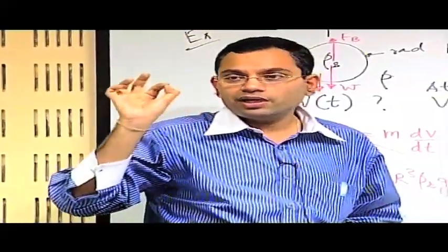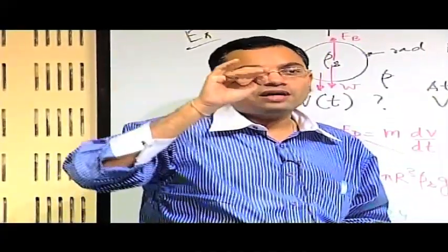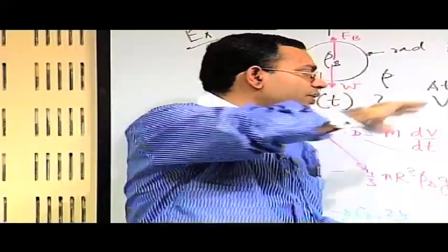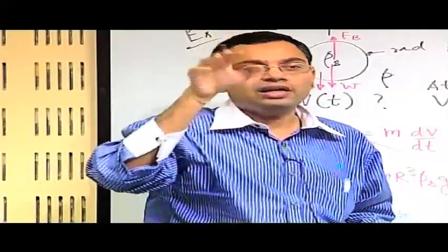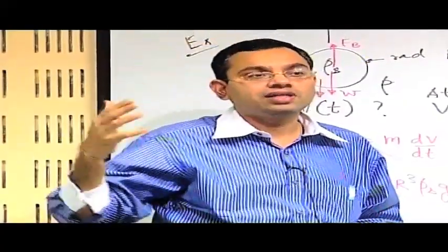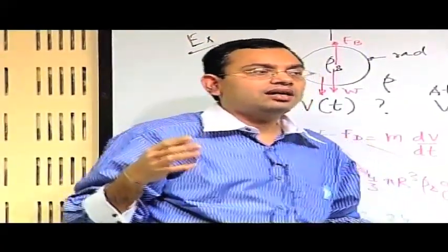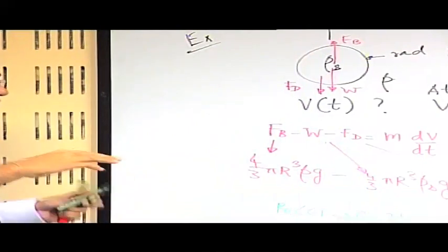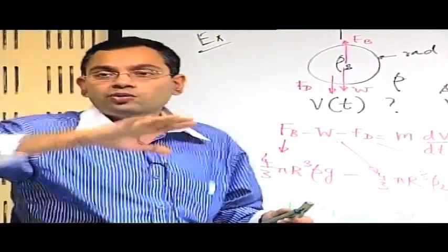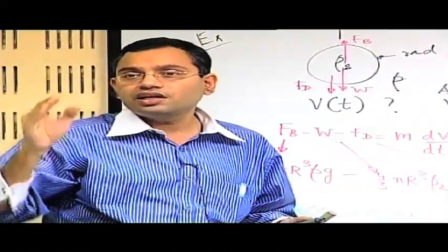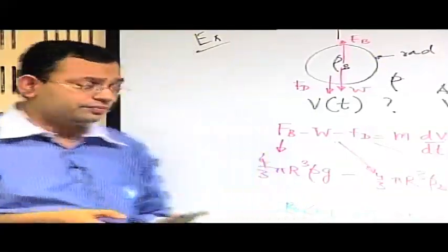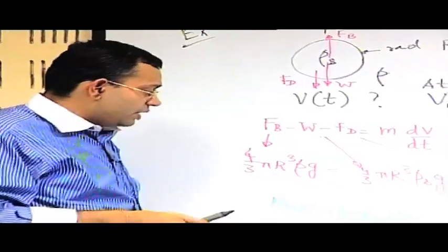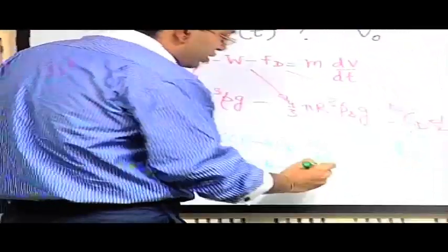So, when the boundary layer becomes thinner, then when the surface effects of the fluid are there, they now penetrate into the outer fluid outside the boundary layer, and they may perturb it sufficiently, and that of course becomes more and more important. So, the form of the geometry of the surface tends to become more and more important as you increase the Reynolds number. Now, at very large Reynolds number, CD is approximately a constant independent of Reynolds number.